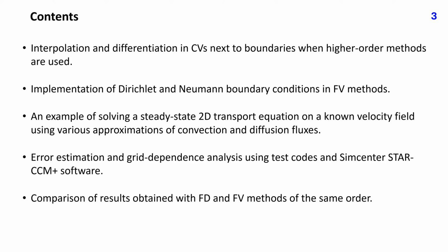Described are two approaches: using ghost cells on the outer side of the solution domain boundary, and adapted interpolation and differentiation methods in cells along boundaries. The next topic is the implementation of Dirichlet and Neumann boundary conditions in higher order finite volume methods.